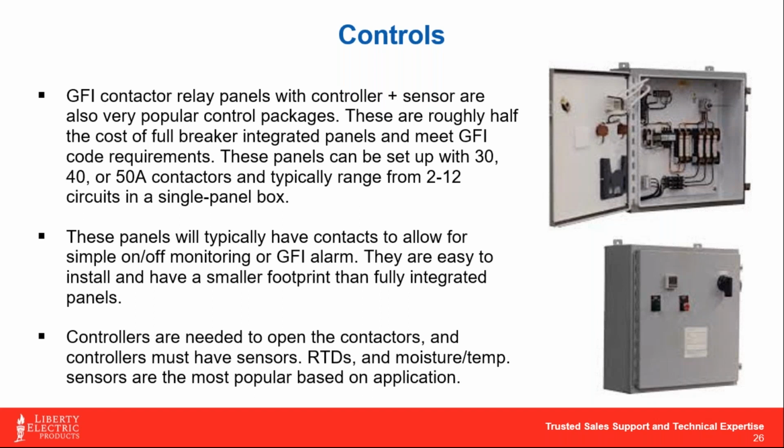Whereas when we talk about taking the skin temperature using an RTD, a thermocouple, something of that nature, we're actually taking the temperature right on the skin of the pipe underneath the insulation itself, which is going to be a lot more accurate to what conditions the pipe is seeing. So, even though the outdoor temperature may have gotten down to 25 degrees a couple weeks ago, it didn't stay down there for very long.